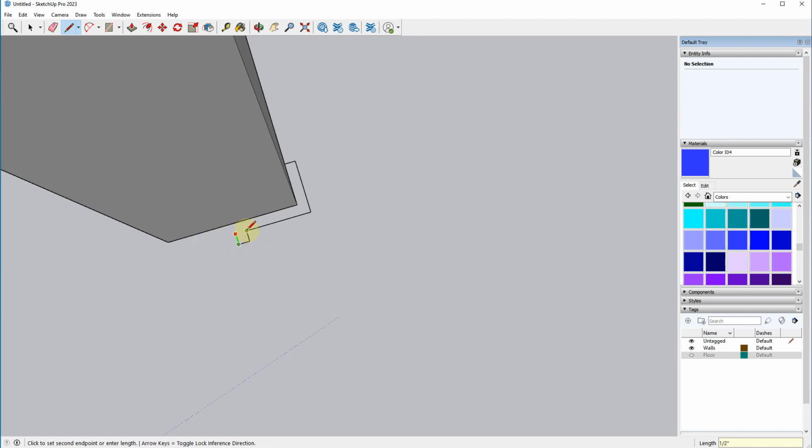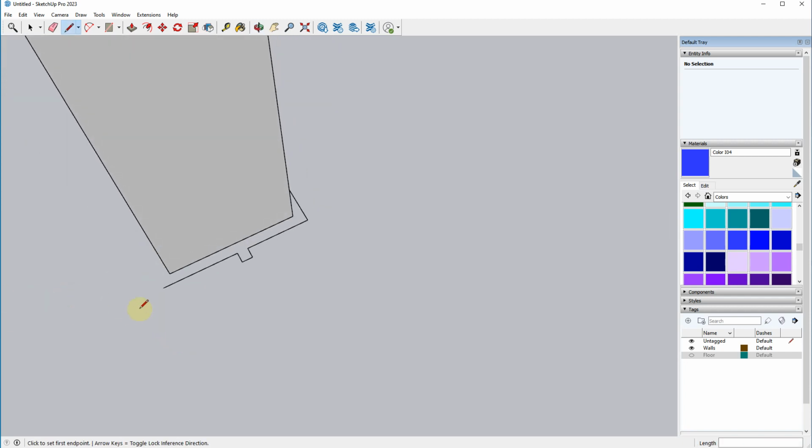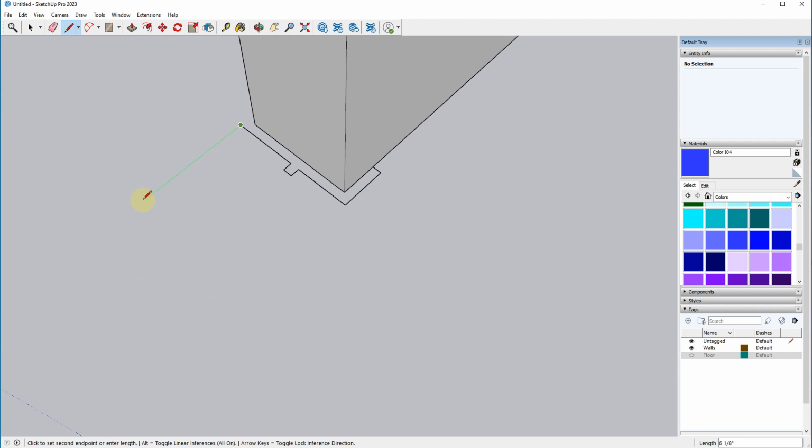What happened there? We'll just lock it there. This distance right here, if I hold down shift, as I showed you guys the other day, it locks it, and it lets me visually see what's down here when I snap there. So it's 3.5 inches. I can do 3.5, and then we'll do 2.5. Or in fact, I could snap it. Oops, not green. We want green right here. And then I can match it up so that it matches here.